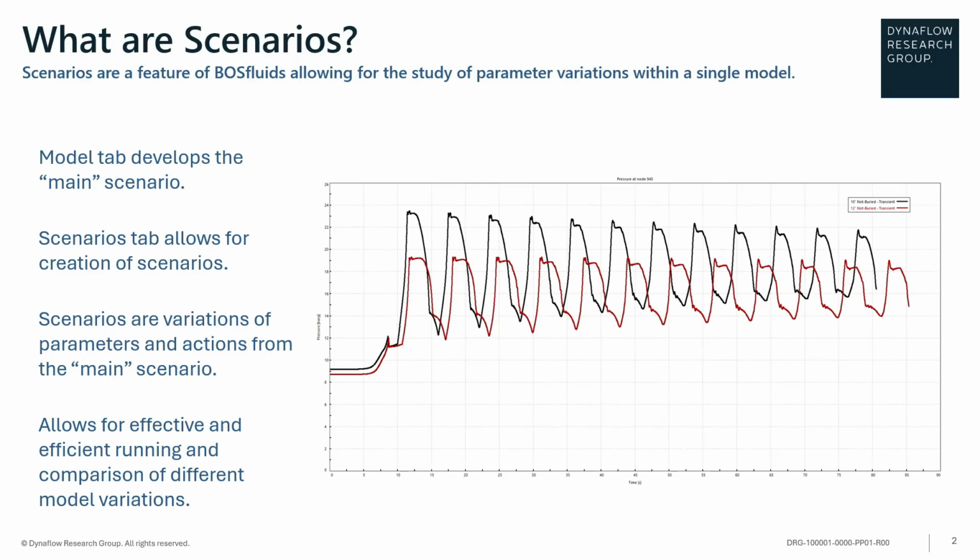This tab allows the creation of scenarios, which are essentially copies of our main scenario, where we can edit a large array of parameters without affecting other scenarios. Through the organized use of these scenarios, you can manipulate your model to effectively and efficiently develop and analyze multiple model variations, all within a single BOSfluids file.